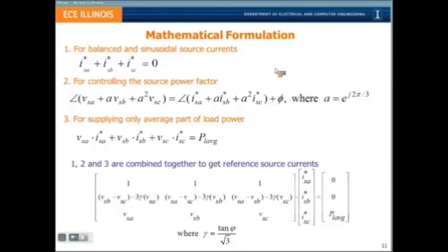One important point to be noted is that zero sequence current has a physical meaning in power systems because it's a neutral current component, but zero sequence voltage does not. When I say va plus vb plus vc equals vn, let's call it some other voltage. It's not the neutral voltage. It's a neutral current here, but it's not the neutral voltage, and it holds good only for one case. You can use Millman's theorem to prove that.